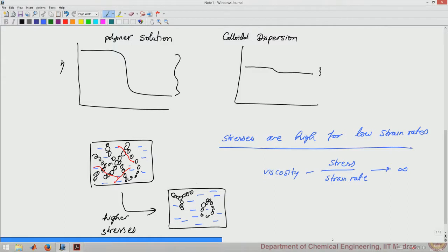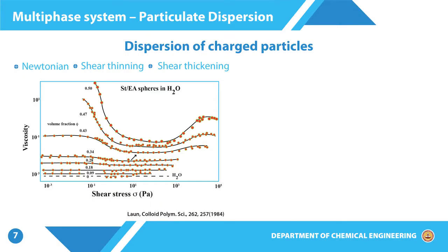So, therefore, we again have a system in which the viscosity is observed to be higher again, which implies that again there is either a percolated structure or a jammed structure, in which case particles find it difficult to move about with respect to each other. And this phenomenon is even stronger when a higher concentration of particles, almost 50% of particles in water, is prepared.